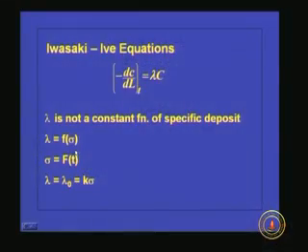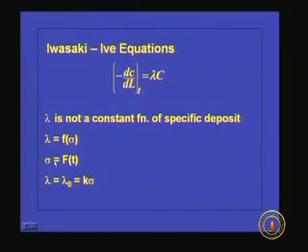With high velocity, whatever particles are already attached to the filter media will be sheared off and come along with the liquid. So, to a certain extent, the filtration efficiency was increasing with respect to time or specific deposit, and after that, the filtration efficiency will be decreasing with respect to the effluent quality. That is what is written here.